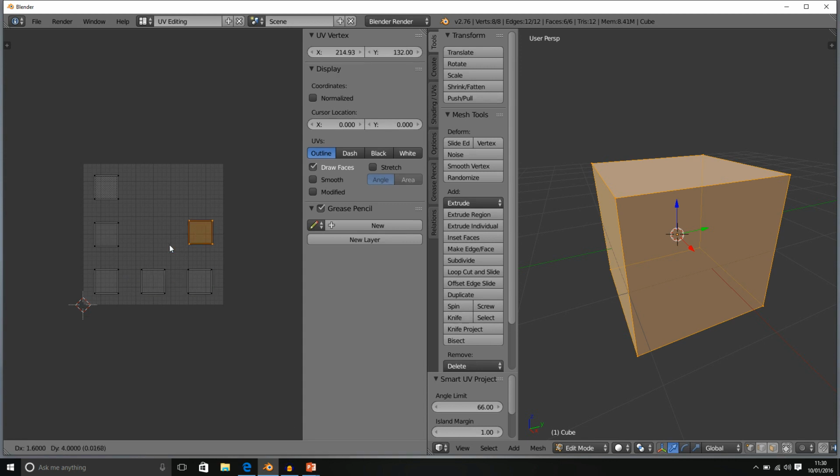As a result, Blender has had to remark the seams so that every single face is disconnected. This is brilliant because now we can select islands, move them about, and resize them however much we want. Let's have a look at a couple more examples of Smart UV projection, and we're just going to worry about the primitive meshes for now.